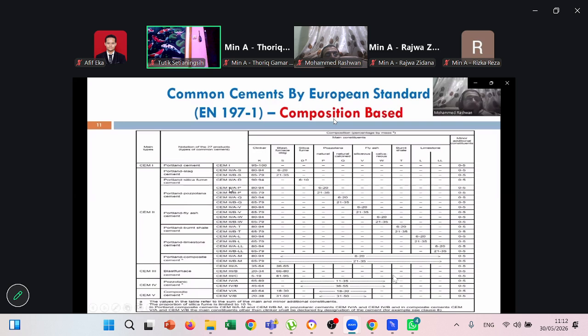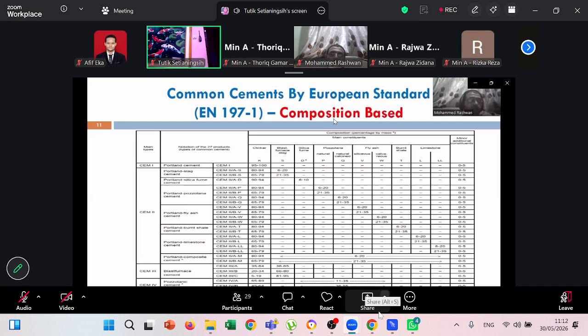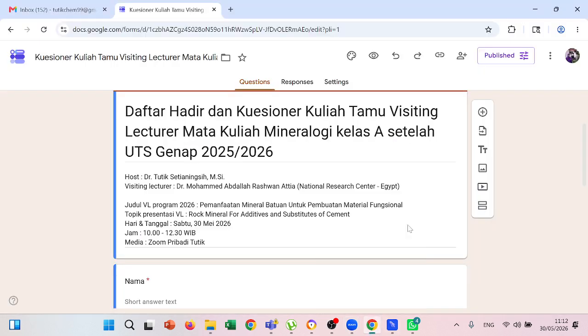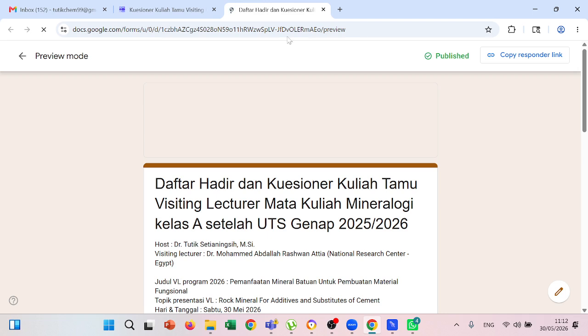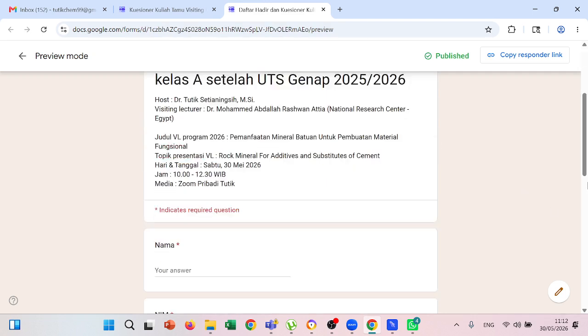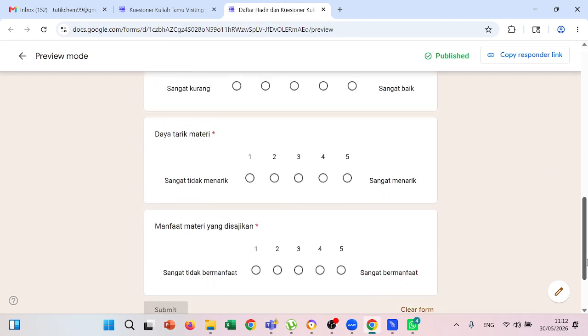And for pozzolana cement, there are subdivisions, as mentioned, according to the percentage of clinker and the percent of the natural pozzolana, and the type of pozzolana, whether natural or calcined, and so on. And simply, from top to bottom, we can see that the amount of clinker decreases, and the cement name is reversing.